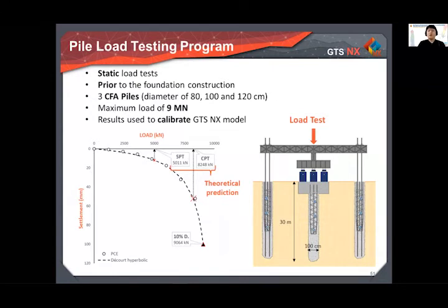In this slide, I will show you some results of pile capacity prediction based on the cone penetration test. So here we are heading to the pile load test program. The static pile load test, just to define, is composed of a real scale pile, which is tested by applying load, and at the same time, the settlements are recorded for each load step.